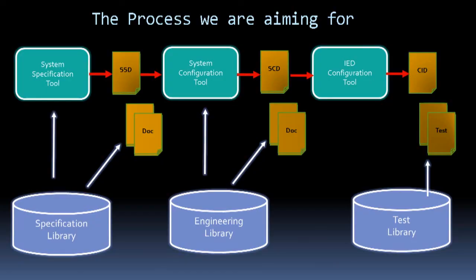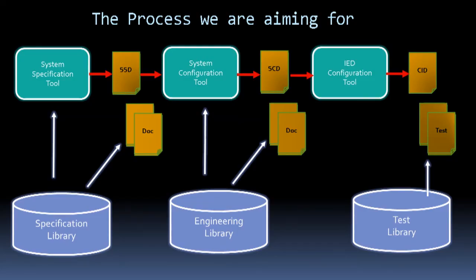We can do it for smaller applications today without a big problem with all the different vendors. So edition 2 supports this really now. If we have very big systems with more than 100 IEDs, this still is a little bit clumsy, so there we need maybe some additional ideas. But based on such a work, we will have much, much more efficiency. And the key of this efficiency is to have all the engineering knowledge in these libraries. So it has been done once, it can be reused, it is formalized, and similar substations really result in similar solutions, which is very good for the maintenance.